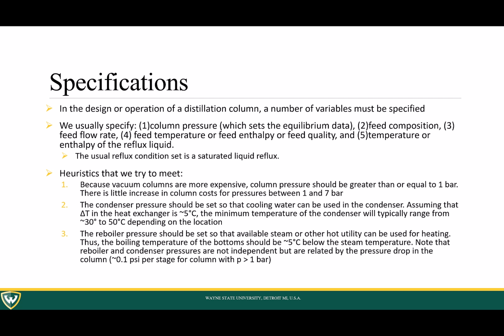The feed flow rate, the feed temperature, or the feed enthalpy, or the feed quality. Or you can also specify the temperature or enthalpy of the reflux liquid. The usual reflux condition is set as a saturated liquid reflux.